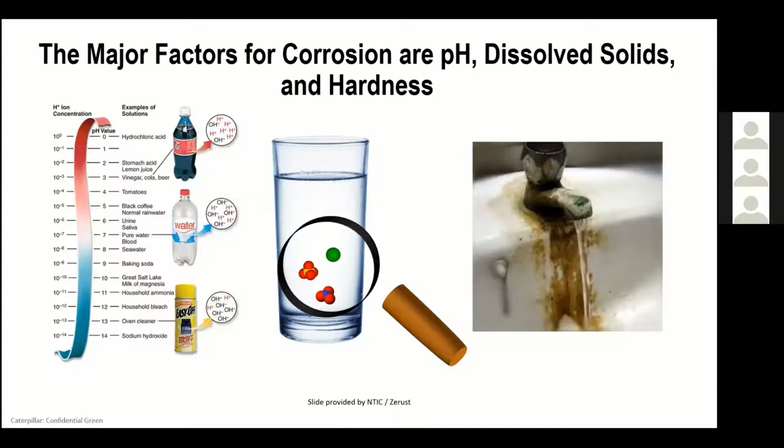There are two other components here that I want to talk about. The next one is hardness. When you hear the word hardness, that's really the calcium and magnesium in your water. Most people here in the Peoria area, since we have fairly hard water, will have a water softener. If your water softener isn't working, or if you don't have one, the easiest way to see that you have issues is probably in your dishwasher, where you'll start seeing some spotting. Some of the products they have will tie that up with what they call chelating agents.